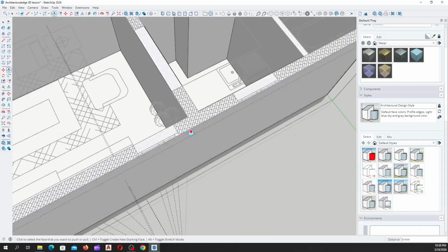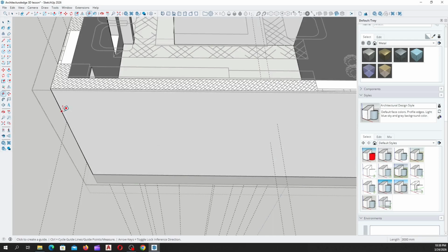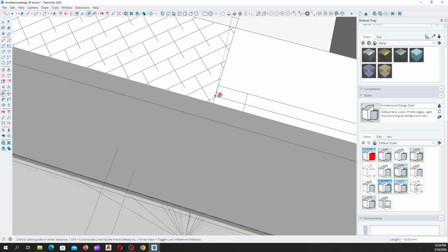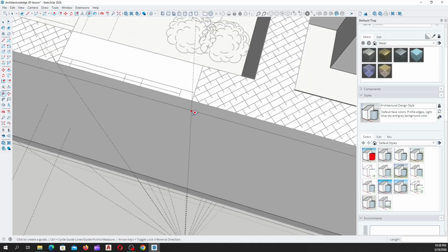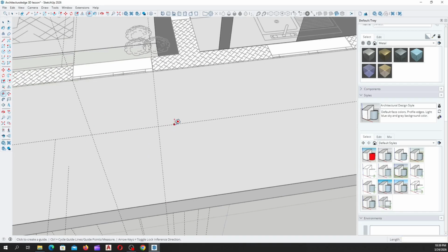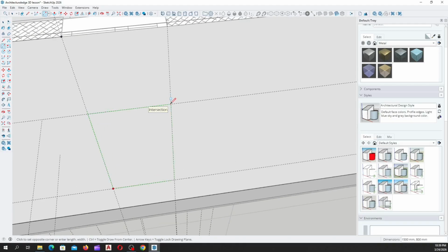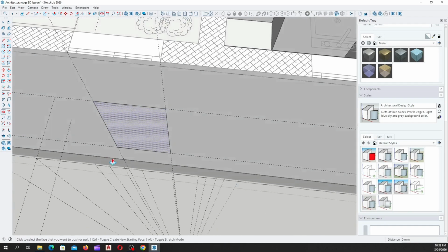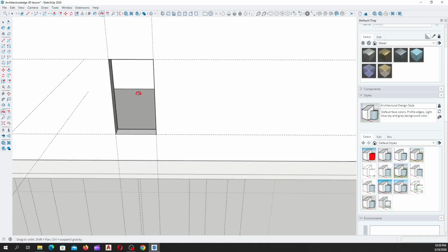All right. Then we'll come to the rear view of our floor plan. So we can pick from this place. Then we snap it to this point. We also pick here. We snap to this point. Then we offset 1200. Enter. Then the height of our window 1500. Enter. Then we'll pick our right angle tool. Then we enclose the mapped out area. Then we offset, we snap it here. We have our opening here.